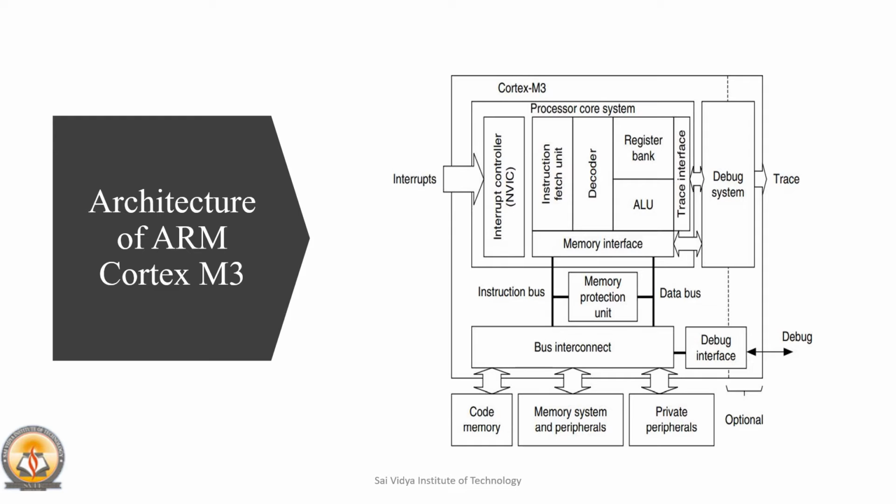The highly configurable NVIC is an integral part of the Cortex-M3 processor, and it provides the processor's outstanding interrupt handling abilities. In its standard implementation, it supplies a non-maskable interrupt and 32 general purpose physical interrupts with 8 levels of preemption priority. It can be configured to anywhere between 1 to 240 physical interrupts with up to 256 levels of priority